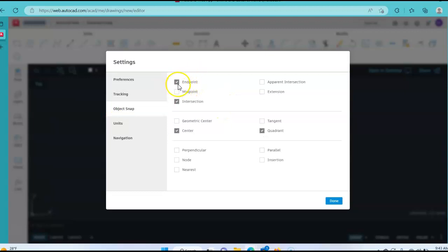So here's our object snaps. Again, you can select these, and at this point you should be aware of how to turn some of these on and off. Looking at exercise 9, the extruder cover, we're definitely going to need the center, maybe intersection, maybe endpoint. Actually, quadrant, looking at that, none of our intersection points are really in a quadrant, so shut the quadrant off. But we will be using the tangent, since we have some features that are at the tangent.